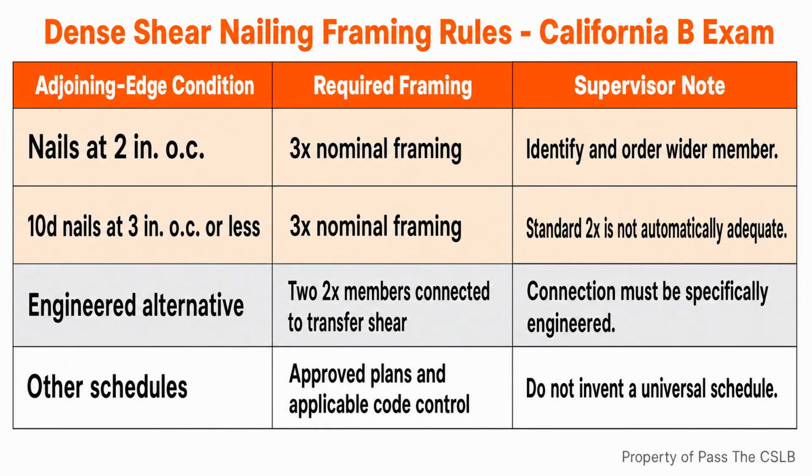Air pressure, tool adjustment, and operator technique can all affect nail seating. I do not need to guess which cause is present. I need to see the pattern, stop the production defect, verify the tool and setup, and keep defective work from being covered. A useful memory pair is this.